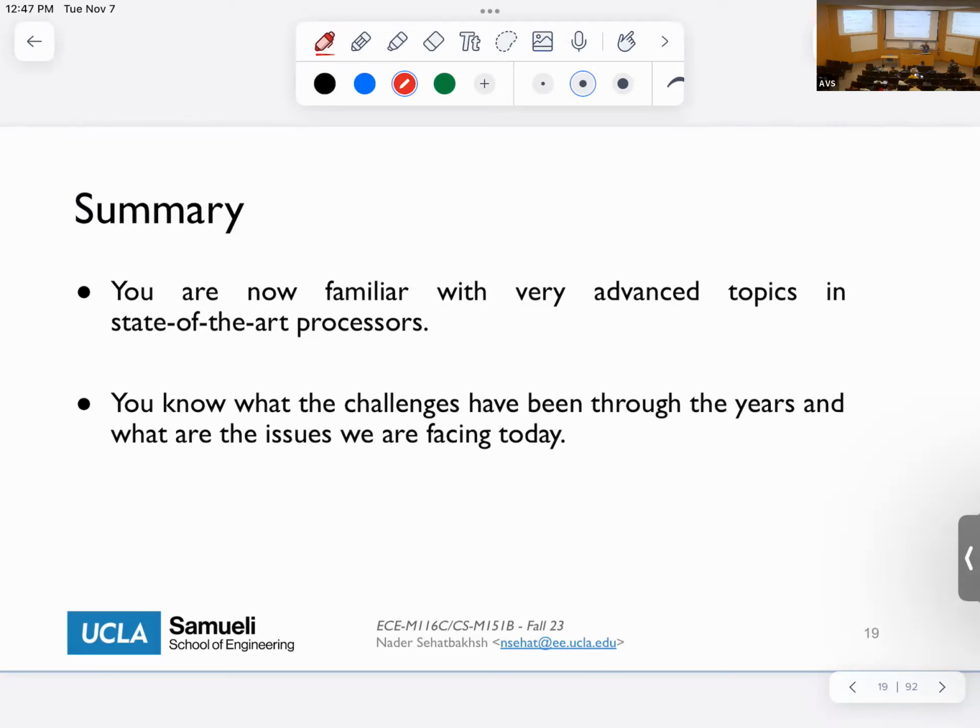But what you will see at the architectural state is only things that have been retired. You will never see which instructions are completed. You will only see the retired instructions. So that's why there's a distinction between architectural state and microarchitectural state. Microarchitectural state, the programmer does not have any idea about, okay? We don't know whether there is forwarding. We don't know whether there are stalls. We don't know any of that. The only thing that we do know is that I can read my X0 to X31. I can read my memory. I can read my PC. Those are all the things that I can see. But we're actually going to talk a little bit about interrupts later on in the class.